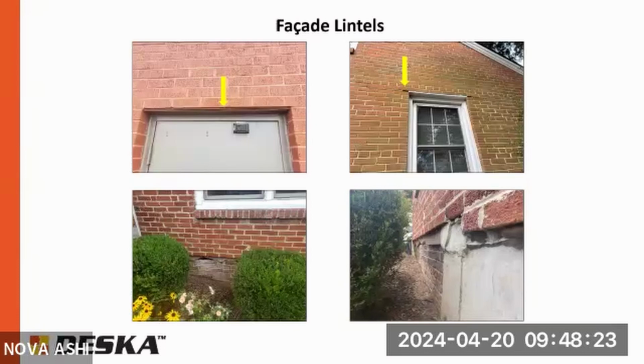When you replace the outer lintel, do you often or not have to replace the inner? Usually not, because it's a little bit more sheltered from the elements being on the inside. But when the exterior one is removed and you can see it, if it's corroded, then we would make that recommendation. And sometimes there isn't one. If it's full masonry, there would be one. If it's a timber frame stud wall, then you would only have an exterior lintel. Also, depending on the type of construction, sometimes they should be flashed as well and have weep holes above them to prevent any moisture from building up behind the brick facade. But that just depends.